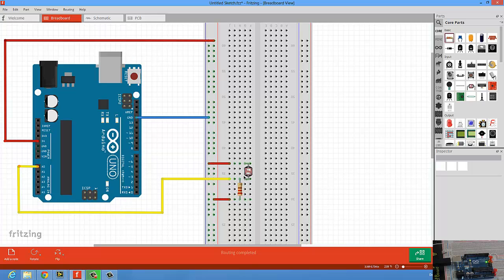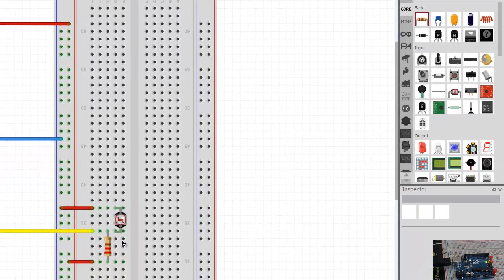So this sensor changes its resistance according to light, but the Arduino board can only sense voltage change. So what do I do? Simple. I use a simple voltage divider circuit. One resistor is constant here. This one is going to be 10K, and the other is a variable resistor, which is going to be the LDR. So as the LDR value changes, the voltage will change, which will be used to show that there is a change in the light intensity.